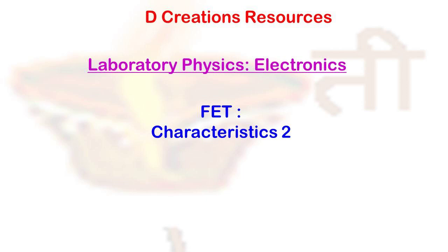For most linear applications, the bipolar transistor is the preferred device. However, the unipolar transistor, that is the FET, is much more useful where the input impedance is expected to be very high. The typical JFET has an input resistance in the hundreds of megaohms. This is the big advantage that JFET has over the bipolar transistor, and it is the reason that JFETs excel in applications in which a high input impedance is required.